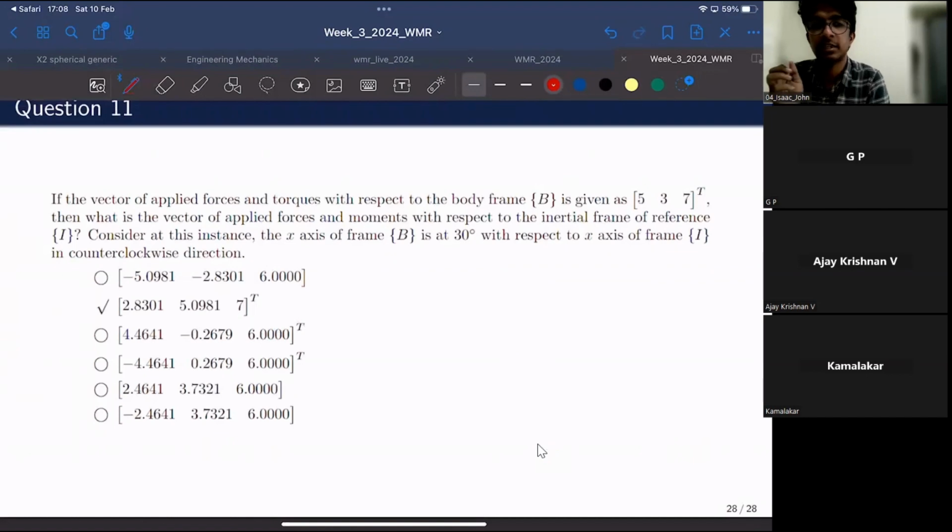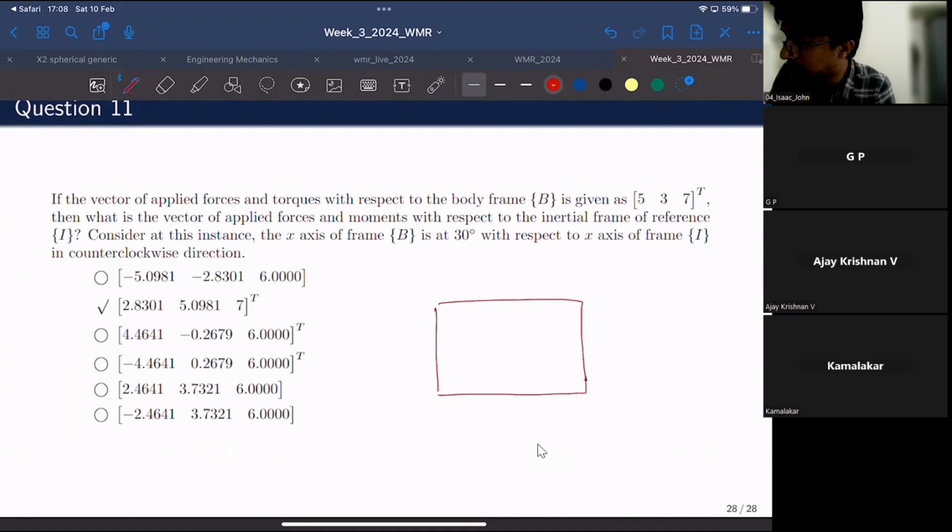Oh, okay. That is the reason why the mobility is two, because mobility is nothing but the degree of maneuverability plus the degree of steerability. For example, if this is the robot that you're talking about, a differential wheel robot, this is the example that you're considering, right? A differential wheel robot.